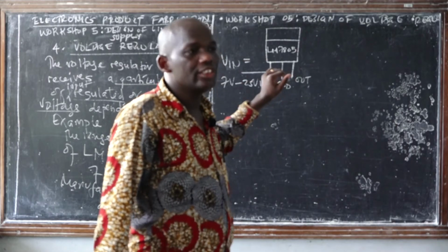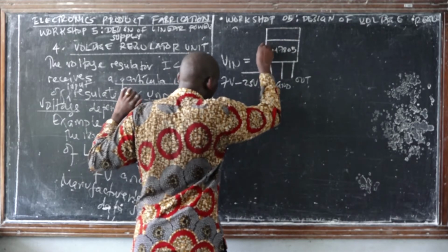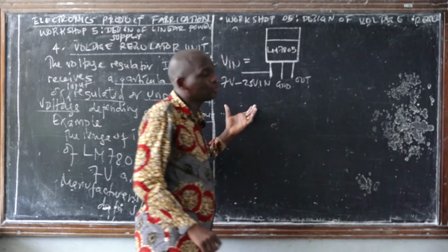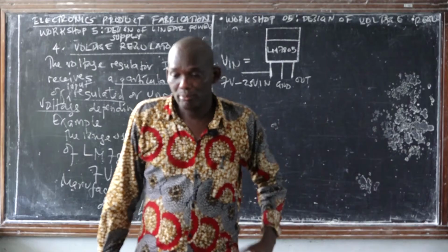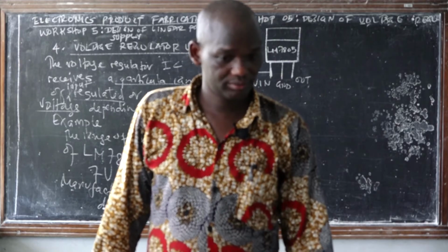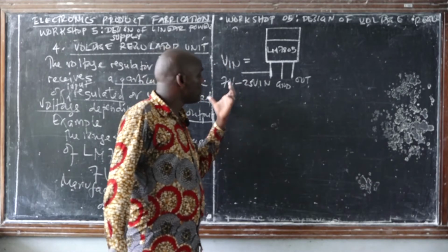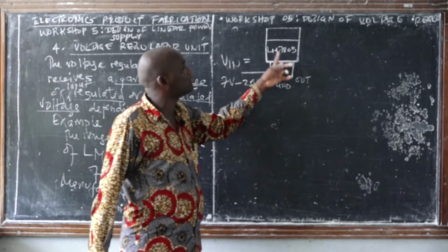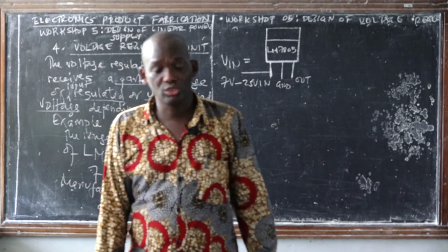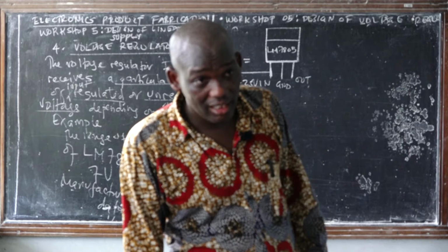But practically, you might find that you have designed your linear power supply. Today it's providing 5 volt, then you turn off your circuit, you leave, the next day when you come back and turn it on, you measure the output voltage and it is not 5. Maybe it's 3.5. Don't expect the other parts that need 5 volt to work. If you provide an input voltage of more than 25 volts to the LM 7805, you are going to burn or destroy your voltage regulator. Class, are we together?